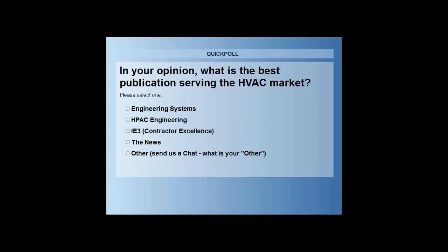If you have the recommended pressure differential, then you know that your detector installation should perform correctly. Another thing to note is most duct smoke detectors that are installed in rooftop units do have to go through an approval process by the manufacturer of the rooftop unit to ensure that that detector is properly installed and is suitable for the location where they have put it. So that's another avenue that you can also go to. You may be able to get some information from the manufacturer of the rooftop unit.